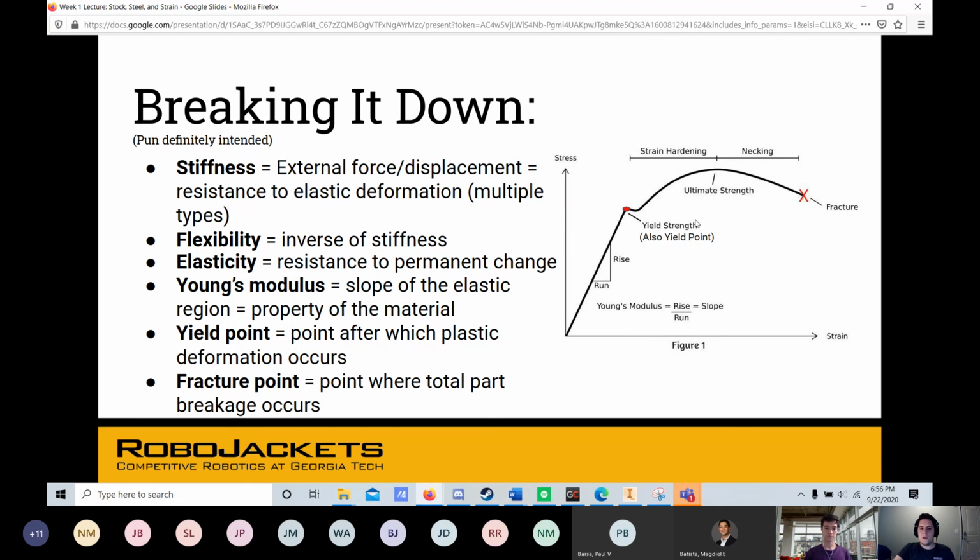And I guess another part that's important is called the fracture point. Even after a material deforms, it'll have a little while until it actually completely breaks off, like in my poor pen's example, right? And we call that just the fracture point. Obviously, that part isn't as important, but in a lot of cases like BattleBots, you'll typically see after a couple matches, your material's already going to start banging up, but nothing has completely snapped yet. But then because of repeated loading and increasing the stresses when you're doing impacts, eventually it'll get to the point where it fractures and separates into lots of pieces. All right.